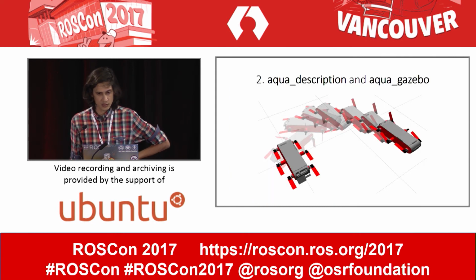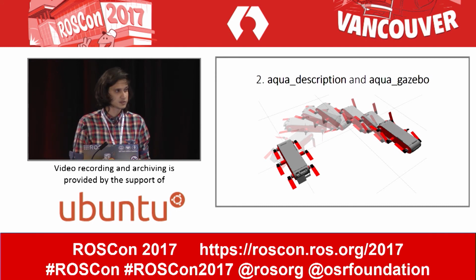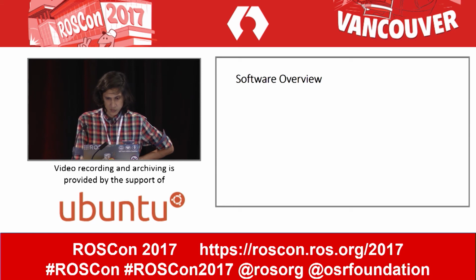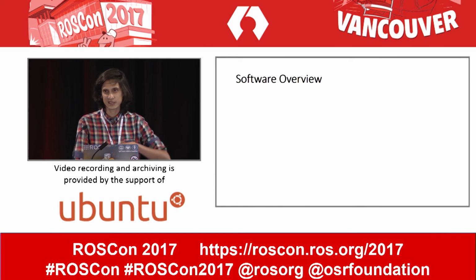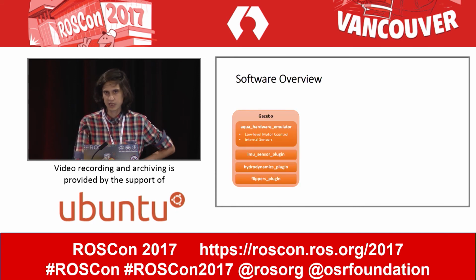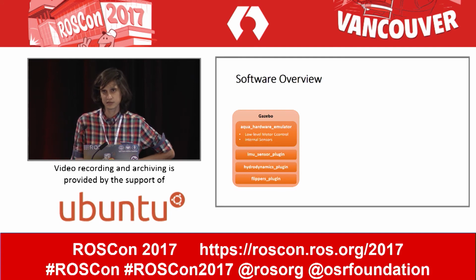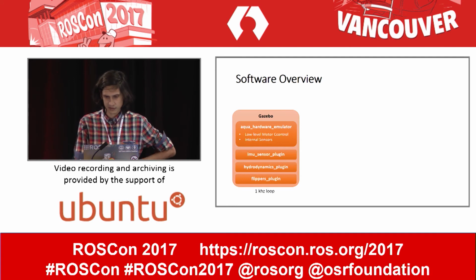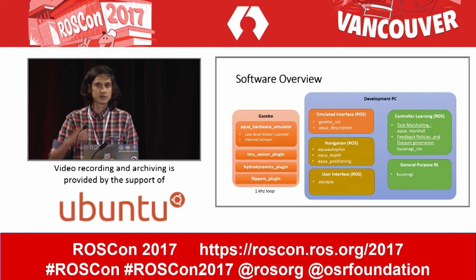So now we can go into the description of our simulated environment that enables a lot of the development and debugging of this software. Going back to that software overview, we just swap out our control stack and our vision stack, and we put Gazebo in. We developed a couple of plugins and use a couple of other plugins that already existed to emulate the AQUA robot hardware and simulate the underwater robot dynamics. That is running at 1 kilohertz, just as the real hardware. And then on a development machine, we just run the rest of our software stack.